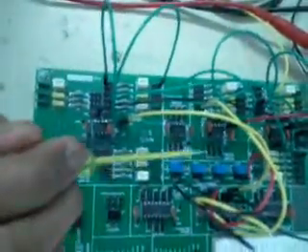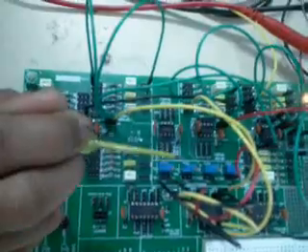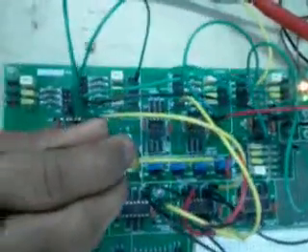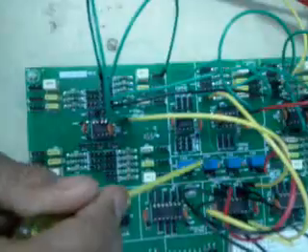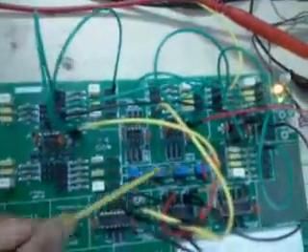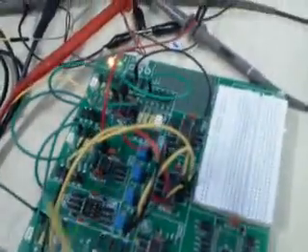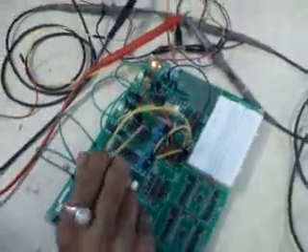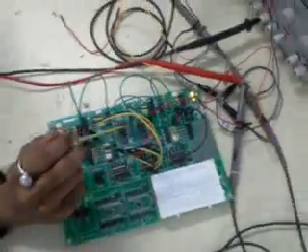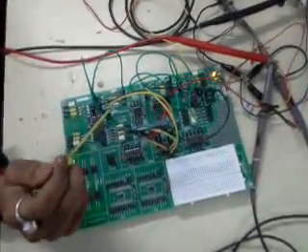Now let us come to the multiplier section. Here for the control voltage we have used port 1 and port 3 out of the 4 ports. The main reason is that at port 1 and port 3 we get the positive voltage at the output, whereas at port 2 and port 4 we get the negative voltage. So we have to use only port 1 and port 3, and for them we have used 1 volt and 5 volt respectively.